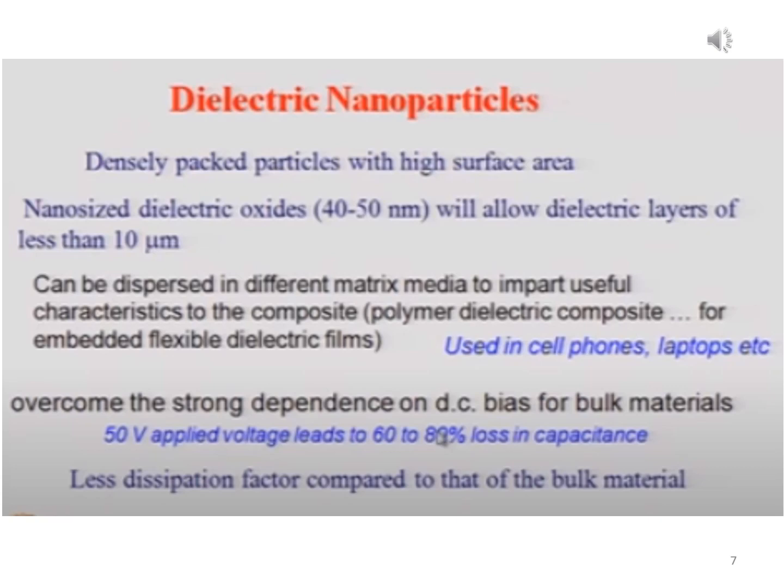Another factor that is important is the lower loss of dielectric nanoparticles. Lower loss means a lower dissipation factor. So dielectric nanoparticles will have a much lower energy loss, or a lower dissipation factor, as compared to micron sized dielectric material or bulk dielectric material.